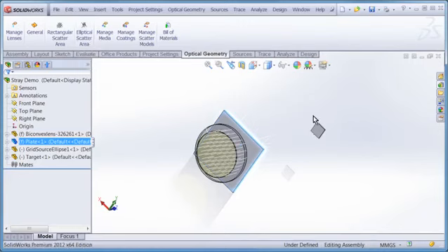So in this particular case, if I'm concerned about scattered light reaching my target surface here, what I'll do is define a scatter area in the vicinity of my detector, scatter light towards that, doing another ray trace. But what Apex will do is adjust the ray distributions so that all of the light gets scattered towards my target, but it will adjust the energy in those rays to reflect the amount of energy that would enter that angular region as defined by the scatter model and the geometry of the system.